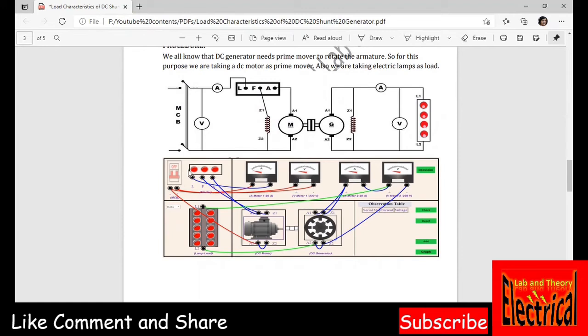The field winding, you can see here, the F portion is connected to Z1, and then the A portion or armature portion is connected to A1. It is also connected to A1, and between this Z1 and A1 it has the field winding, and then Z2 and A2 are short circuited here. You can see here the same thing is written there. So from A2 to MCB, one connection is going, right?